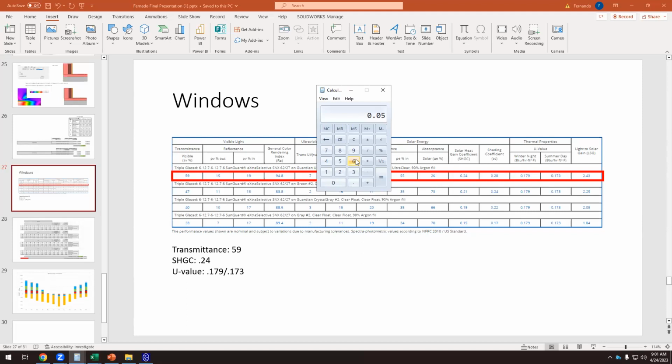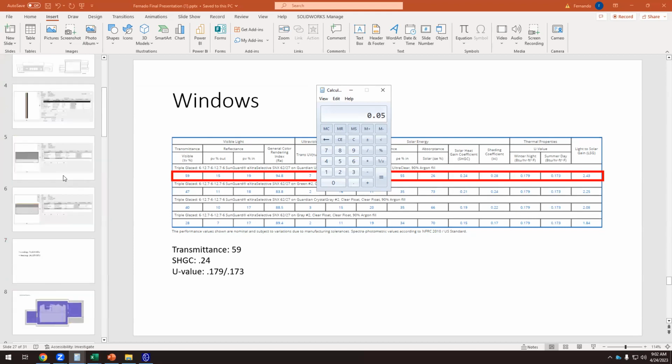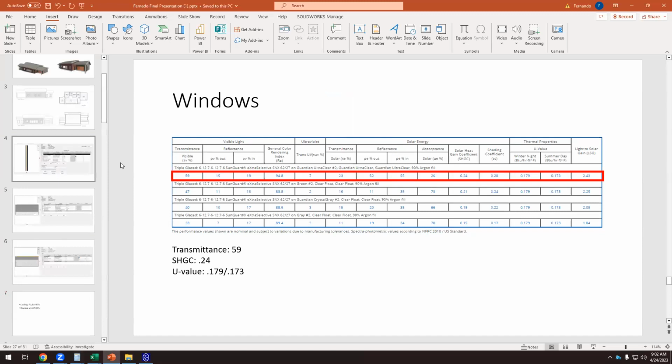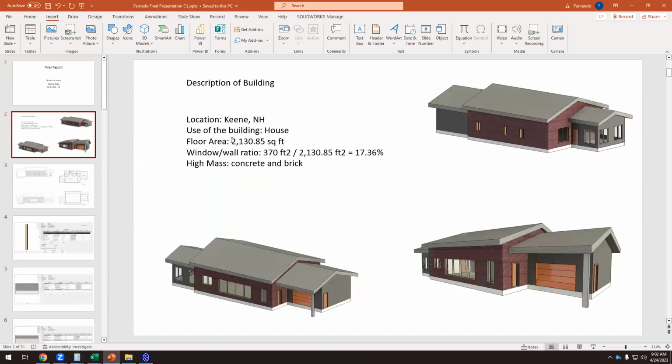We have to add up the U value of different elements multiplied times the area of each element. I'm sure that you know the area of the envelope, the roof. I don't know if you have it somewhere. You have the U value, but we have the window to wall ratio.